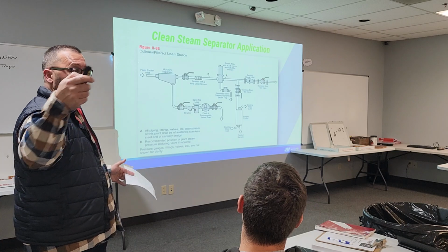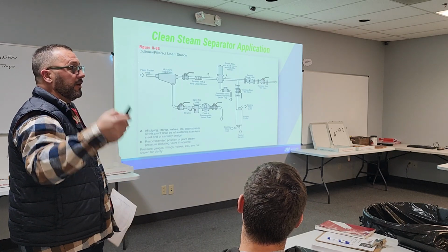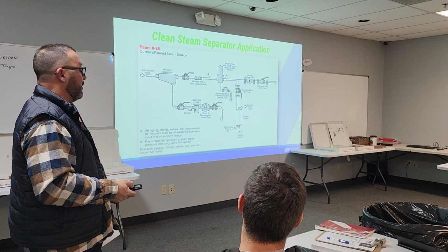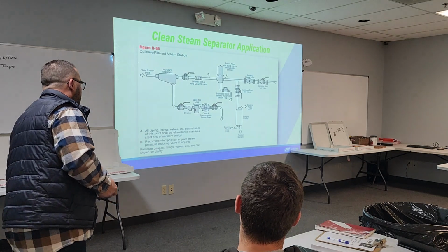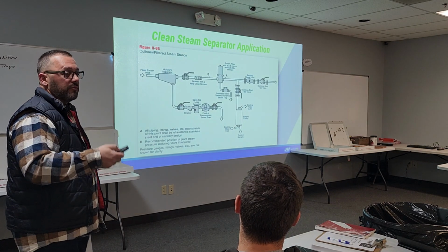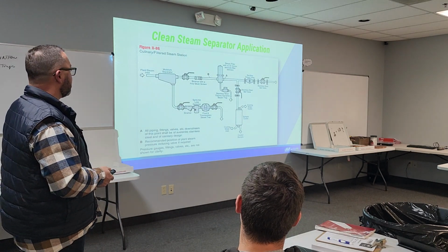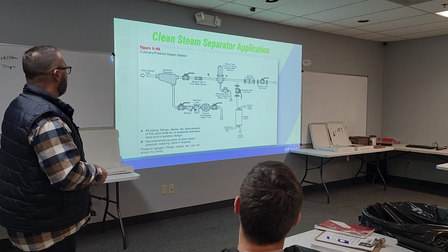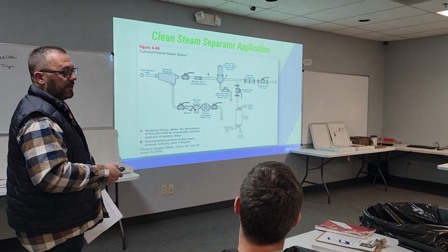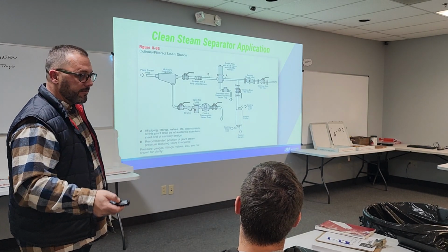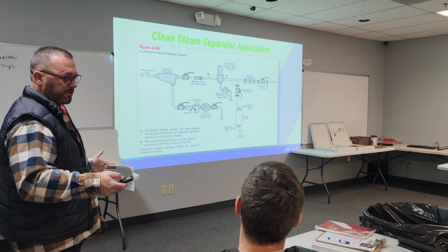We use HART gateways, and they're wireless. These things channel hop. They'll go so many feet, and some wireless gateways you can get 100 devices, some you can get more, some you can get less. But where it really makes sense is if you're a food plant or you're Abbott Labs, and you've got a critical batch process.